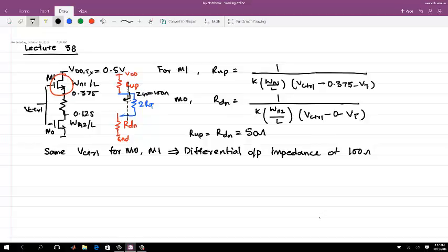Which means even in a case when R up is, let's say, 60 ohm and R down is equal to 40 ohm, even then the differential impedance Zn is equal to R up plus R down. So in this case you maintain a differential output impedance, not a single-ended output impedance. People use both cases, where you can have an independent one and a combined one. The drawback is that if you are not doing it independently, you cannot ensure a common mode termination across the different output voltage.